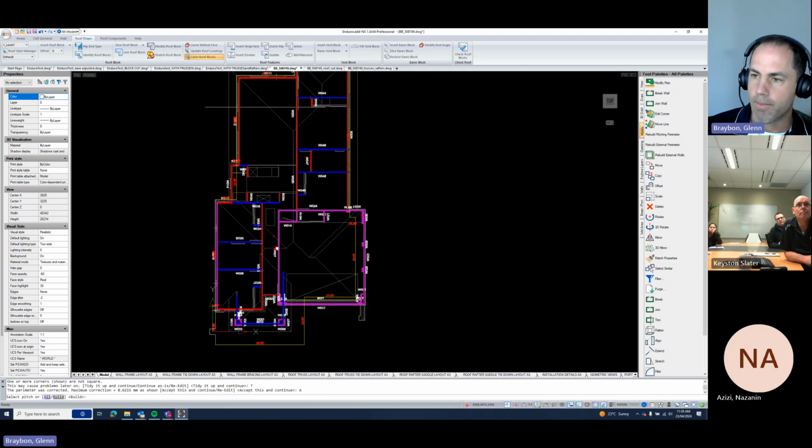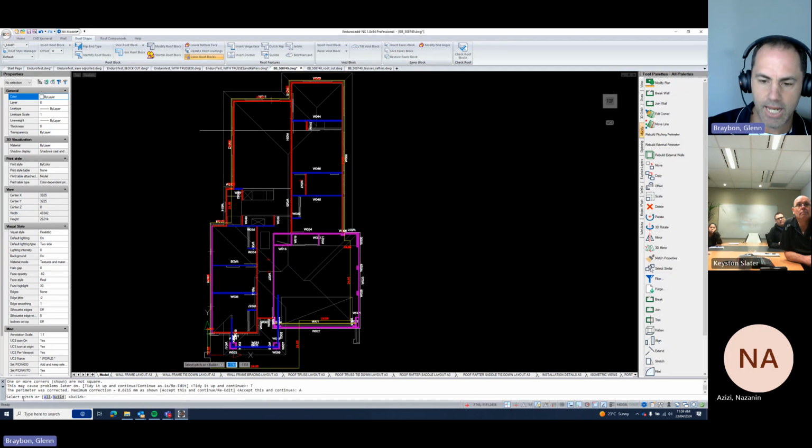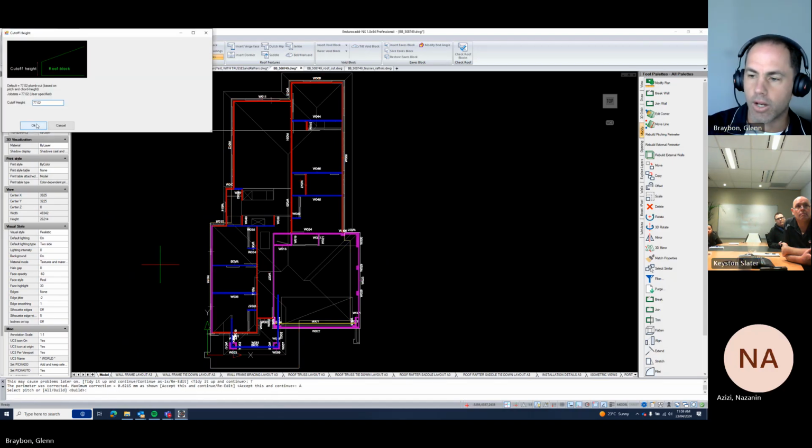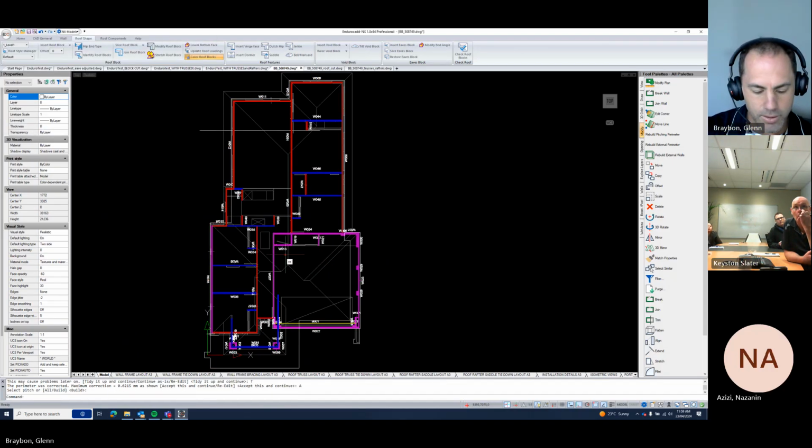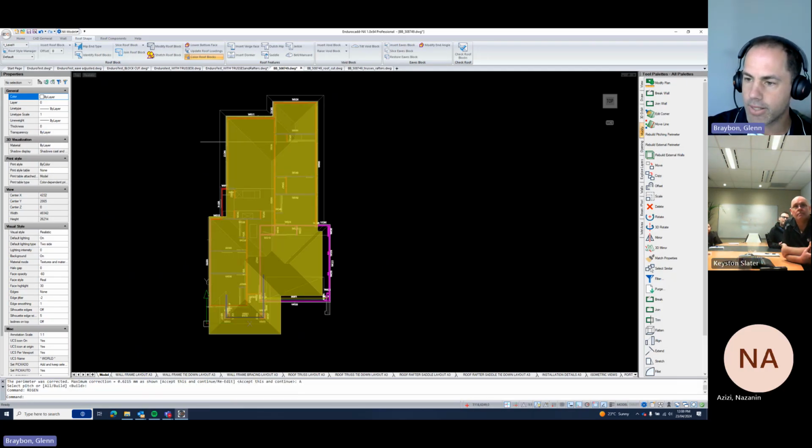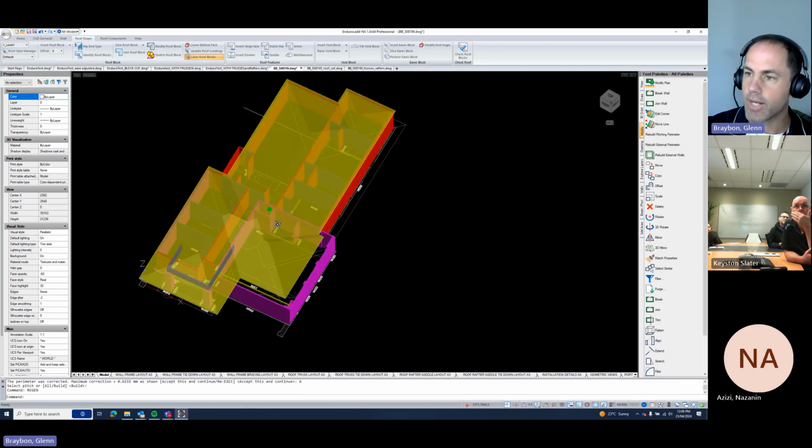All our pictures come up on the screen, and then you can see down here we've got build as our two options. If you want to change the pitch, you can left select one, or you can click all, change the whole pitch, if for whatever reason you've got that setting wrong in your roof construction menu. But build being in the brackets here, if you right click on your mouse, you can see on the cursor as well, it says build with the right click. So right click, okay, build. A little bug there where that roof goes away, but that's fine. So we're looking at our roof shape now that we've built.